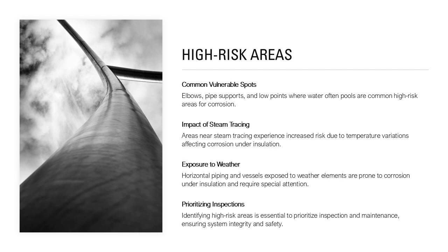Common high-risk areas include elbows, pipe supports, low points where water can pool, and regions near steam tracing. Horizontal piping and vessels exposed to weather are especially prone to CUI. Identifying these areas helps prioritize inspection and maintenance efforts.